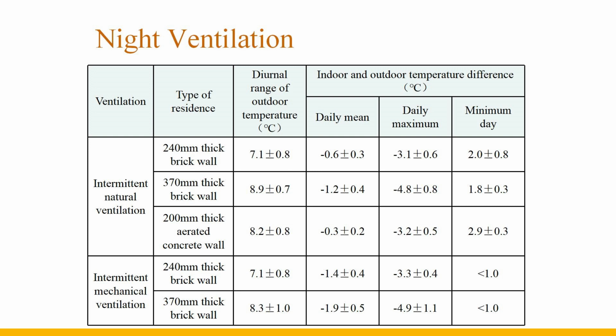By closing doors and windows during the day, the intake of hot air can be avoided, the rise of room temperature can be restrained, and the heat storage of the building envelope can be reduced. At night, dry and cool outdoor air is induced to remove indoor waste heat.